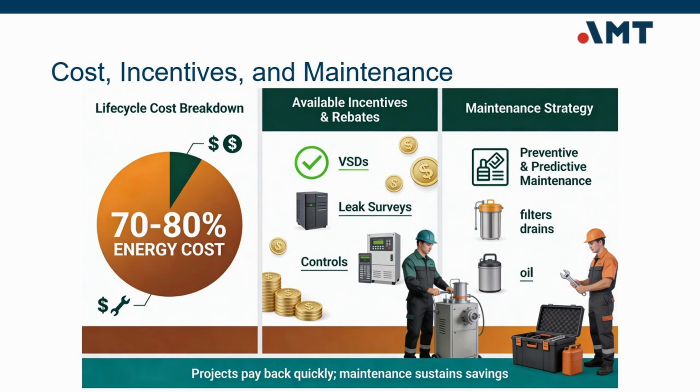But savings don't last without maintenance. A strong preventive and predictive maintenance strategy protects both reliability and efficiency. That includes maintaining filters, ensuring drains operate properly, monitoring oil condition, and regularly checking for leaks.